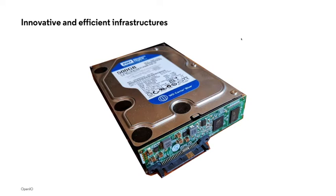This is a standard hard disk, except that in front of it we mounted a small PCB. This small PCB includes an ARM CPU, some flash memory, and 2 Ethernet ports connected to a standard connector that usually is used for SAS communication. By doing so, this very small computer, which is based on Linux, of course, and with the SDS installed, is a complete node. We call it the nano node, and it's self-sufficient.